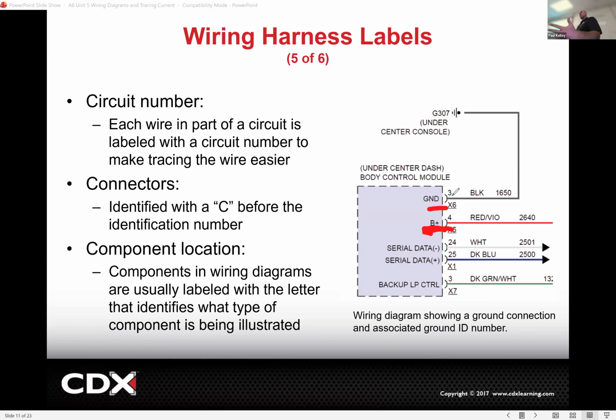That's not like that. How it really is, you're going to look at the wiring diagram and be like, where does it get the power? Oh, terminal 4 of connector X5, and where is that, and where is it located, and then how am I going to check it, and what connector end view, right? And then how does it get ground? Terminal 3 of connector S6. You may very well spend an hour making sure it has 12 volts on 4 and ground on 3 because you got to pull the diagram.